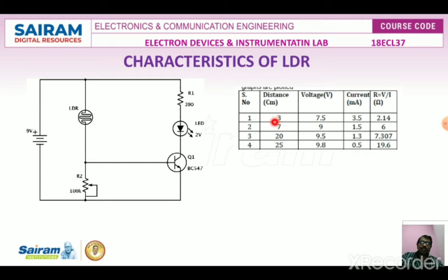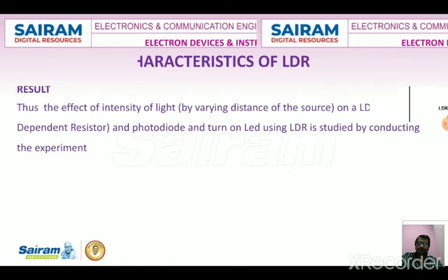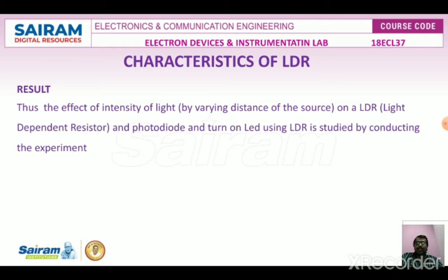By using that we can find the capacitor as 1 microfarad, and R is 10 millisecond divided by 1 microfarad, which is 10 kilo ohm. RF is the diode forward resistance and RR is the diode reverse resistance, of 100 ohm and 1 mega ohm respectively. So R is equal to 10 kilo ohm and T is equal to 1 millisecond.